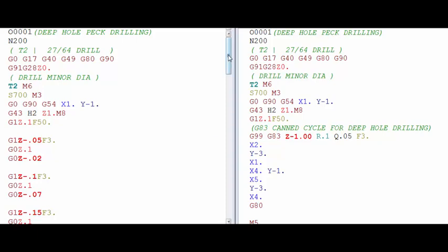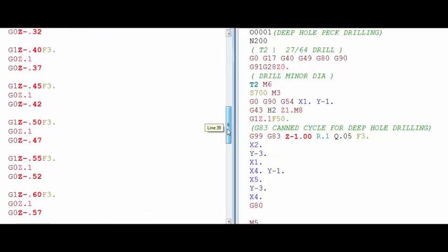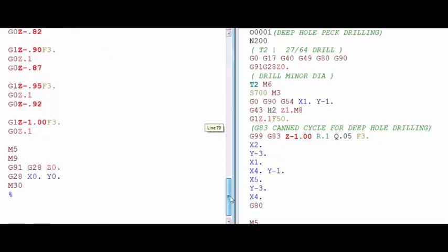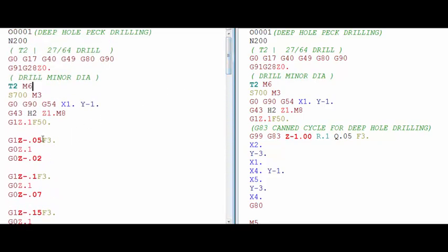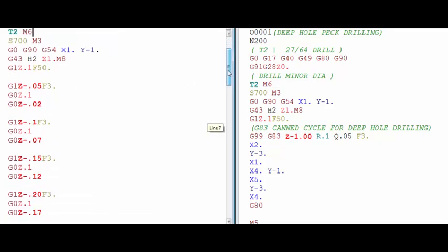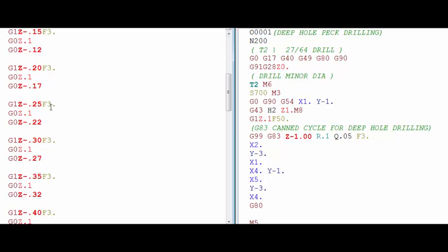So here's another side-by-side comparison of all the code that it would take just to drill one hole 1 inch deep using 50 thousandths pecking. Now if you wanted to change the pecking, then obviously you would have to change every single portion of code, because these 3 lines are a peck, a retract, and then rapiding back to 30 thousandths above the previous peck.